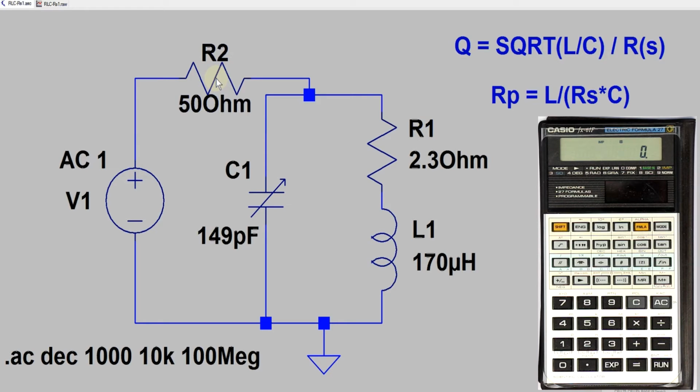The reason is we load our whole tank circuit just with the output impedance of 50 ohms, because here the voltage source behaves like a short, and so we have a direct connection from the upper point of the resonant tank circuit to the lower point via the output impedance of 50 ohms. And that's of course not how we can do it.